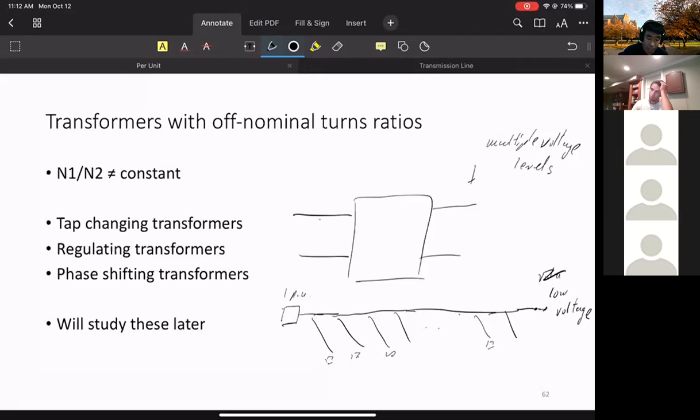So then what we may do is add a tap changing transformer. So add a transformer. And what this transformer does is, depending on how much load we're drawing, this can have a rated voltage of 1 per unit, maybe something that we can step from 1 to something like 1.2. Right?